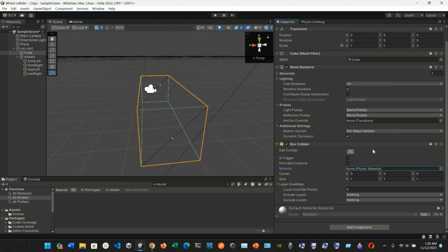Okay, and you can see, let me see, edit bounding volume. Hold Alt after clicking control handle to pin center and place. Hold Shift after clicking control handle to scale uniformly. Okay, so let me see if I can hold Alt after clicking control to pin the center, so we press Alt. Okay, and then hold Shift after clicking control handle to scale uniformly.